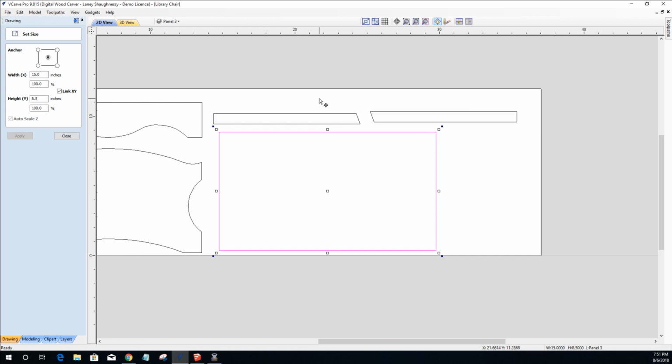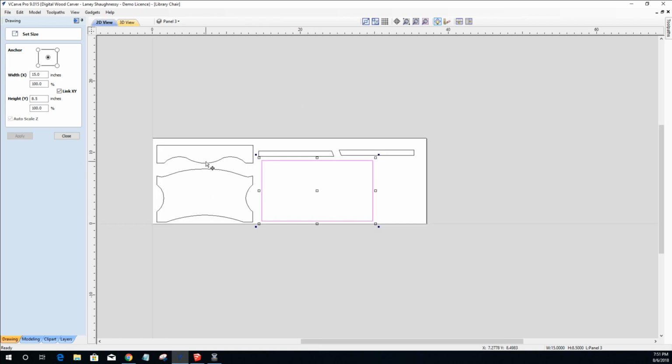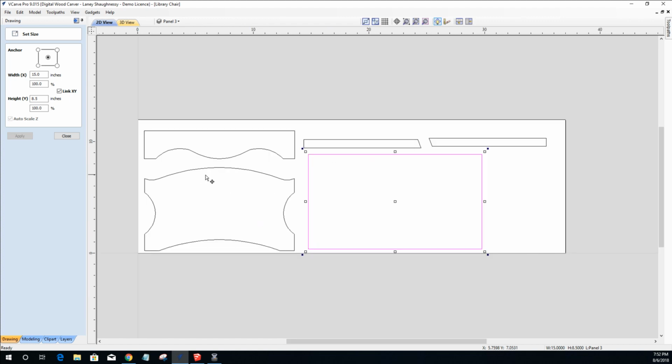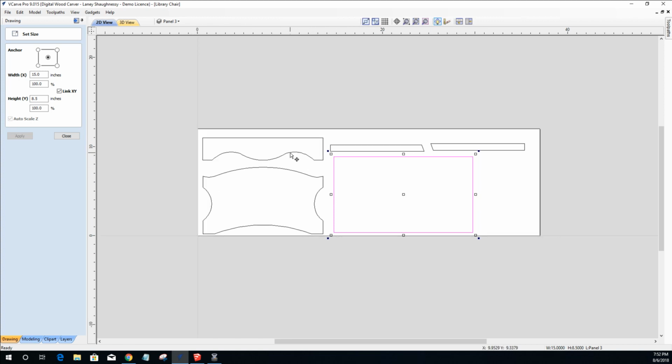It doesn't have to be 12 inches wide, is what I'm saying, for those parts. Any of these parts, they could be cut out of a 1x10, or something. You won't be able to get a 1x8, because a 1x8 is 7.25. So 1x10. But they could all be cut out, other than these 2 parts, the stretcher and the back of the chair, because they do have some ornate curves to them and all.